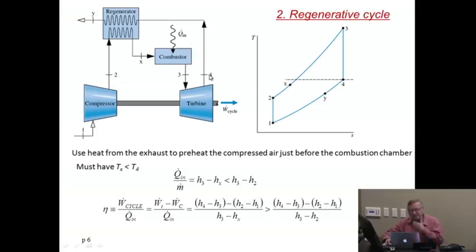So that means that you have the opportunity of taking enthalpy, or heat, out of point number 4 and putting it back into point number 2, in this heat exchanger. So we're going to take H4 minus Hx, an amount of enthalpy that we will feed back in the airstream between the compressor and the combustion chamber, thereby preheating the air at point number X through this heat exchanger.